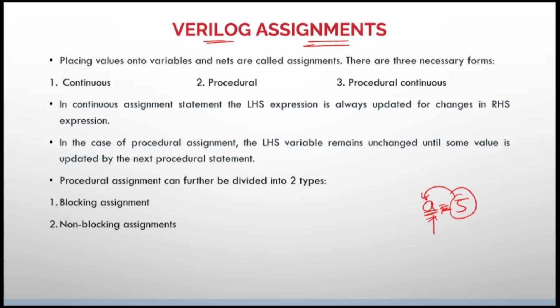Also, in Verilog you have three kinds of assignments: one is continuous assignment, second is procedural assignment, and the third one is procedural continuous assignment. Now coming to what these three assignments are. Continuous assignment is nothing but the assignment that you see in dataflow modeling. In dataflow modeling, the assignment takes place by using the keyword assign, for example, assign c equal to a plus b, right?